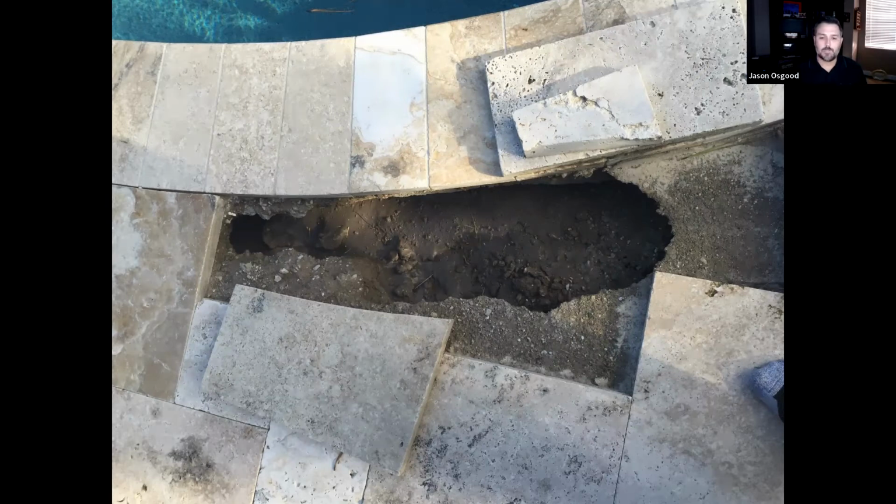But you can see in this picture, this crew did not compact the material very well around the pool shell. And because the paver deck is not a solid concrete deck, the water will wash down in between the pavers themselves. Proper compaction, you're fine. Proper pitch, you're fine. If you don't have that, the pavers, the base material itself will compact over time. Your pavers will dip and it'll be unsightly.